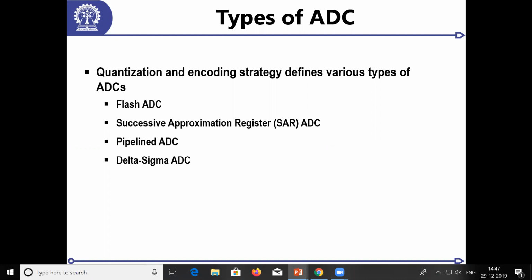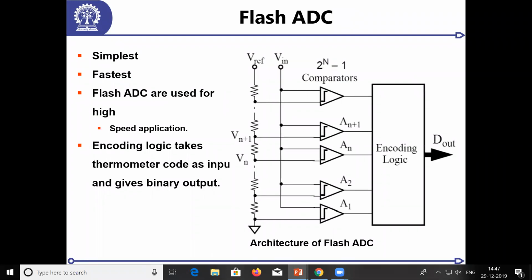So now let's look at what a flash ADC is. Now, a flash ADC works like this. As I said, I'll now switch on to the board a little bit. Let's say I have to digitize, suppose I have a 0 to 1 volt scale. My signal goes from 0 to 1 volt and I need to digitize it into, let's say, 3 bits. So what do we do? This is how I threshold the signals.